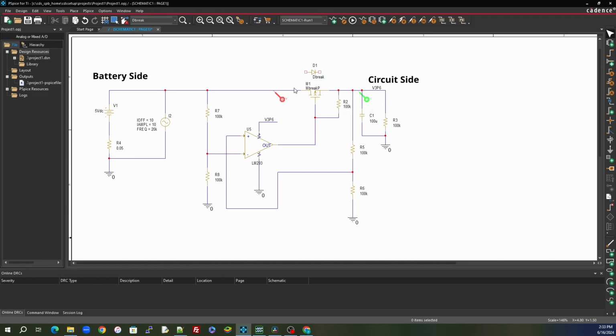If I put this over onto the other side, over here on the drain side, I'll get a weird effect because remember, it's all about VGS. And so if this turns off, my gate voltage is going to be more fluctuating than over here. But I want a nice stable off position, right? So I've got to put it on the source to gate side, not on the drain to gate side.